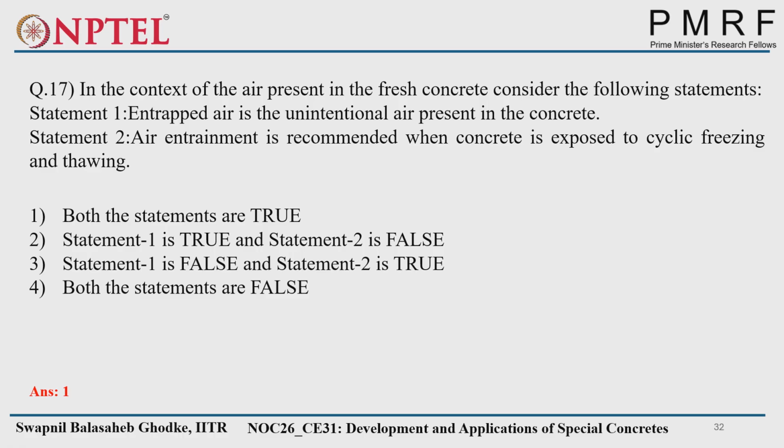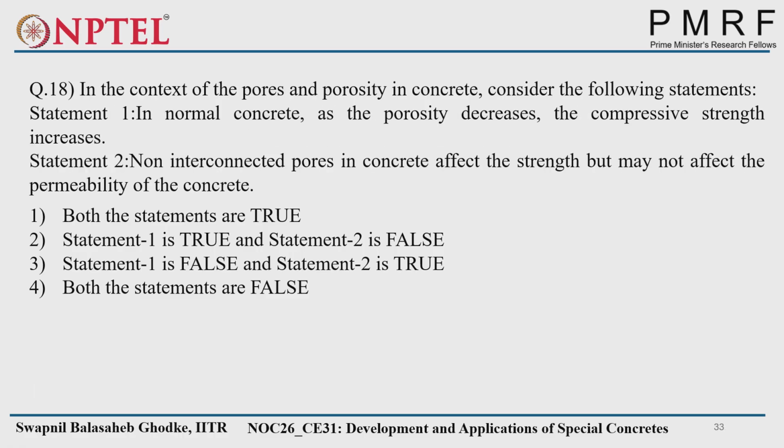Right. So we already saw entrapped air. The word entrapped itself says it's unintentional. We are not intentionally putting it in. Air entrainment means we are putting air in, and it's required when there is cyclic freezing and thawing, which allows extra space for the frozen water. So that's why both the statements are true, and the answer is one.